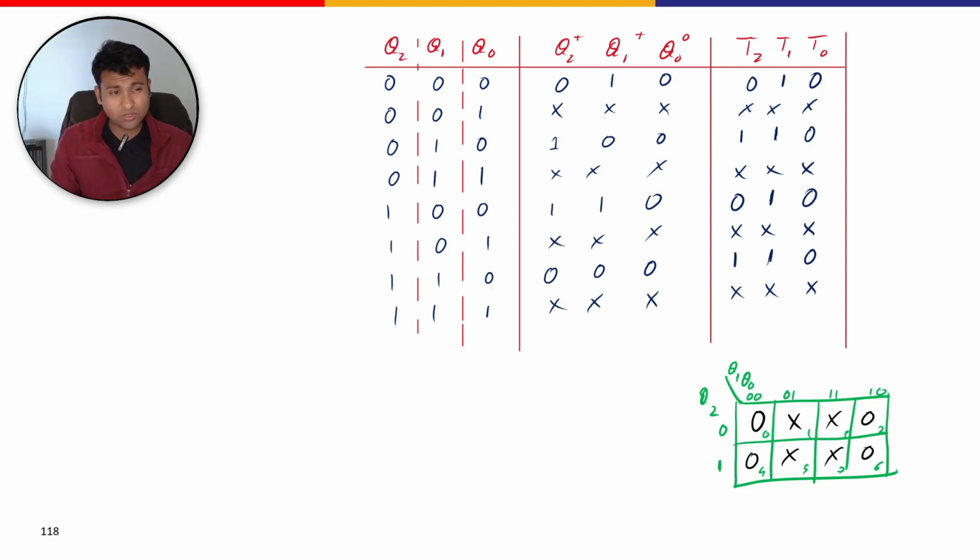Now, I know that many people are tempted to make a grouping of all the don't cares, but as a suggestion, never group don't cares. If you're in an exam, no one will accept this solution. As you can also easily observe, T0 is just 0. So do not club don't cares in any of your exams. The marking will be difficult, but it depends from teacher to teacher. But never group don't cares. So the simple thing coming forward here is that T0 is equal to 0.